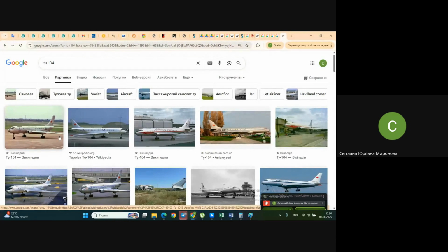One more important consideration, where to place fuel. Typically, as I already said, for passenger and cargo airplanes, fuel is placed inside of the wing, inside of the fin, and if it's a rather big airplane, also maybe inside of the stabilizer. Why not for rather little airplanes, not for heavy airplanes, in the stabilizer? Because the stabilizer is thin in this case.